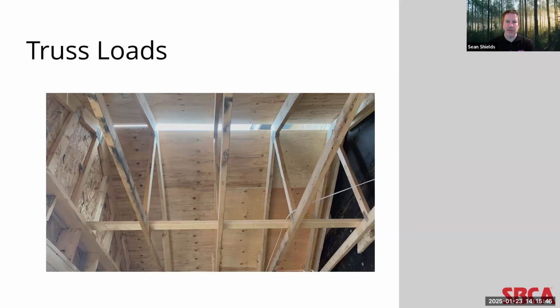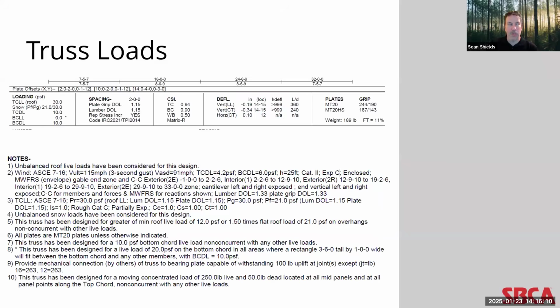Again, you might see this number go higher if the roofing material is assumed to be heavier, like, again, concrete or slate on the roof, or sometimes with floor trusses, they know that they're going to have stone tile on a kitchen floor. You may also see higher numbers if there are known design elements like solar panels on the roof or a kitchen island on a floor system. So looking at the truss design drawing,